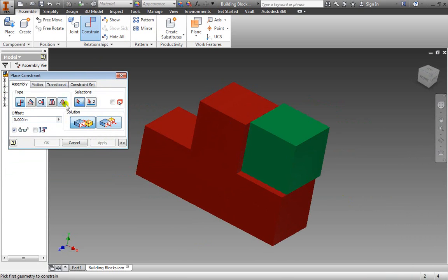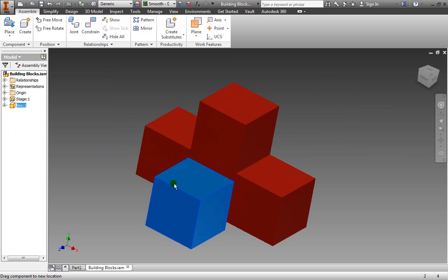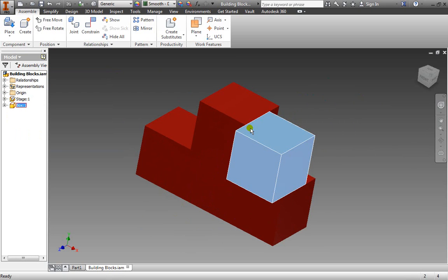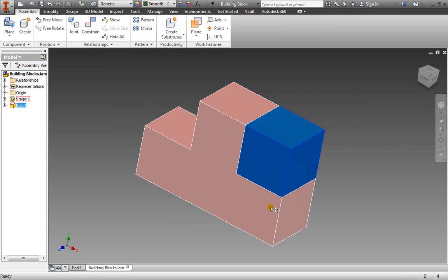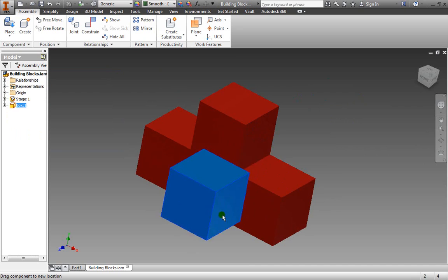And by default, this dialog box will stay here in order to add further constraints. But for now, since we're done, we'll close it again. Now notice that it can only move in this one direction here. Another thing that can help us when constraining our objects, because we may believe if this was perfectly there that we fully constrained our object, but it can move off the block.